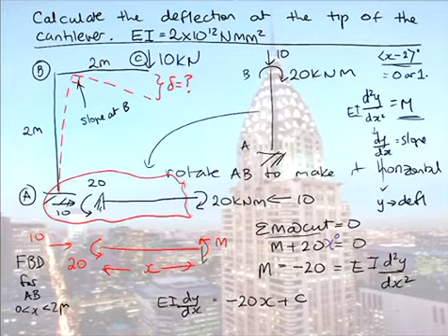Enforce the singularity rule first. A term like that is either 0 or 1, and that's the ability to switch it on and off. So when your moment, as in this case here, is applied a distance x to the power of 0 away, that's always equal to 1. So when you integrate that, you just get x. There's no need for me to include that, but if you like to be consistent, you can say every time I have a moment, I multiply it by distance to the power of 0. We've been through this, hopefully that rings a bell.